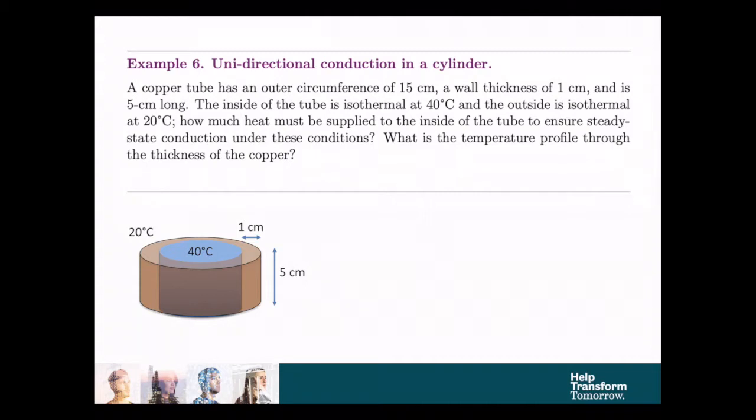And the question asks us, how much heat must be supplied? And so the heat question triggers us to use Fourier's law. The second part of the question is, what is the temperature profile? And so the words temperature profile trigger us to use the heat equation. So this example will demonstrate both the use of Fourier's law and the heat equation applied to a cylindrical geometry.